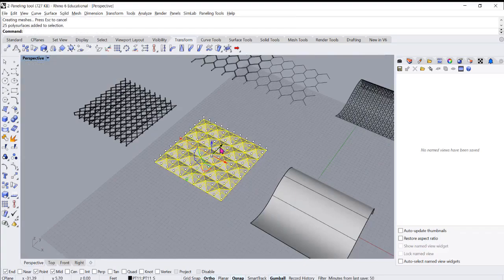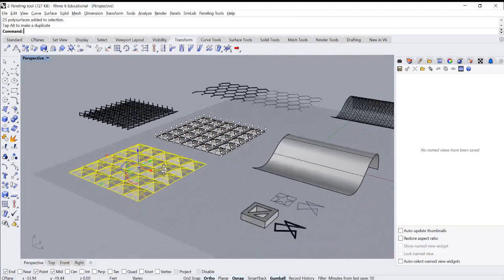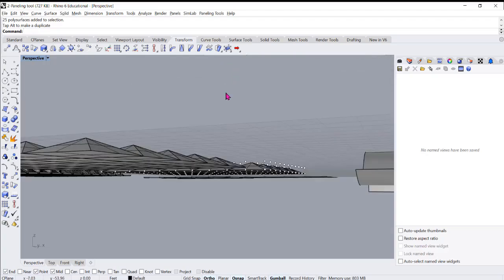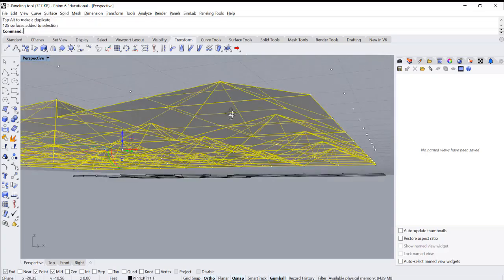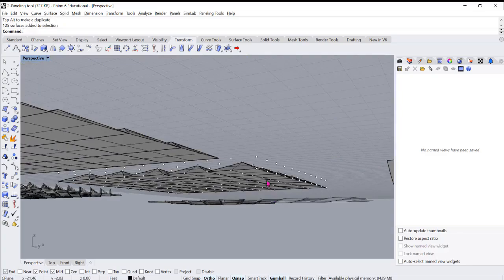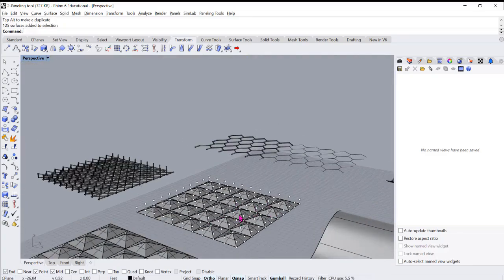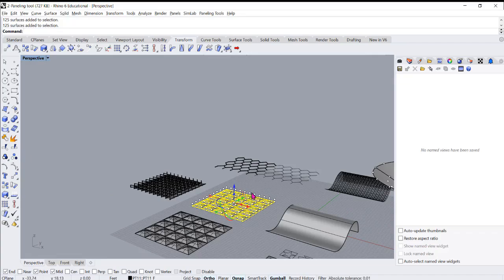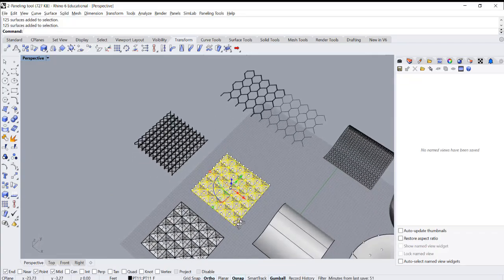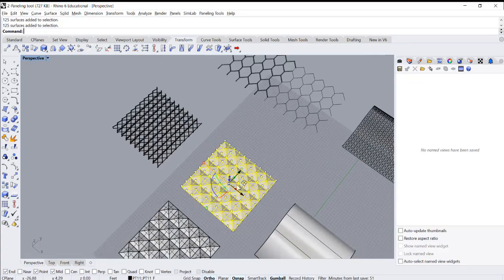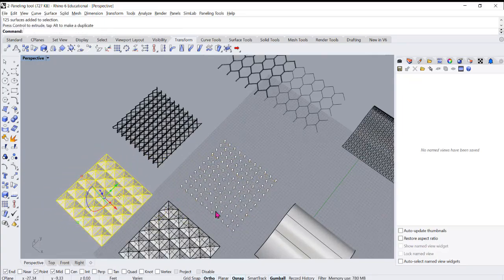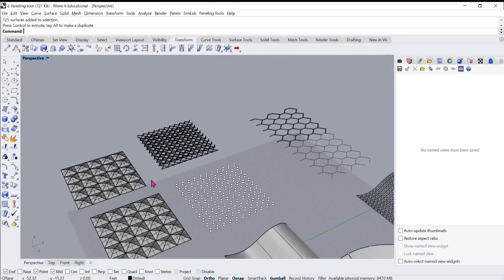See how there are two groups. One was made of faces, and the other one is made of solids, because I had add faces, and the other one had add solids. So it's two calculations. Therefore, it will give you two objects in there. That's why I only had add faces before.